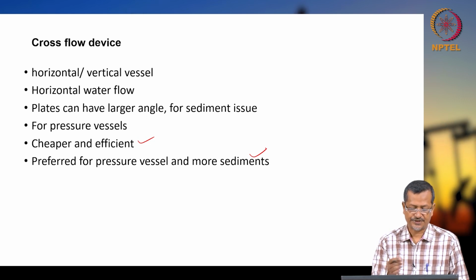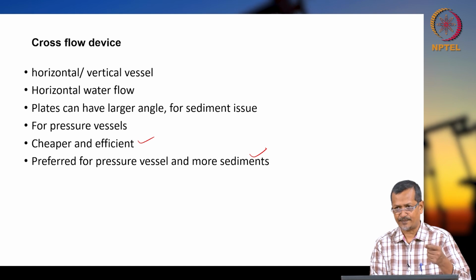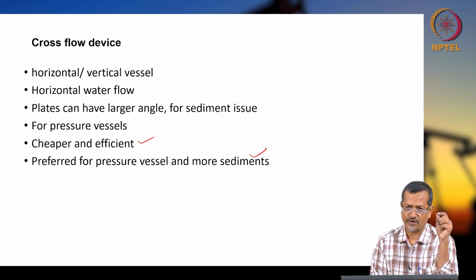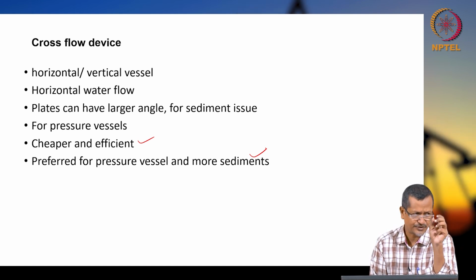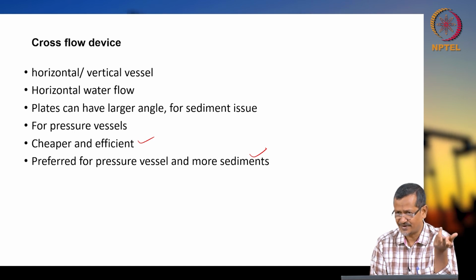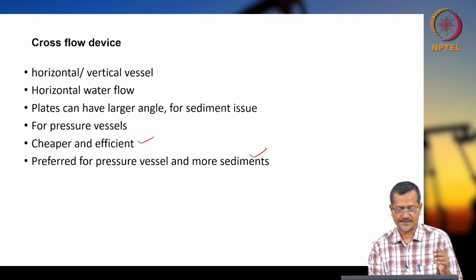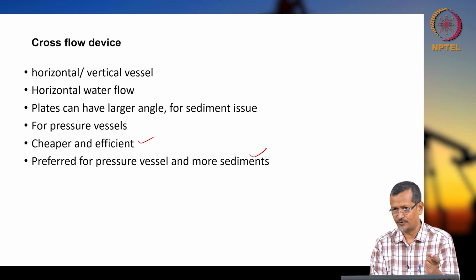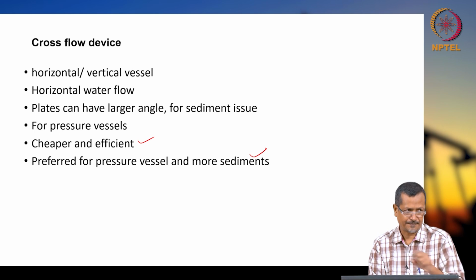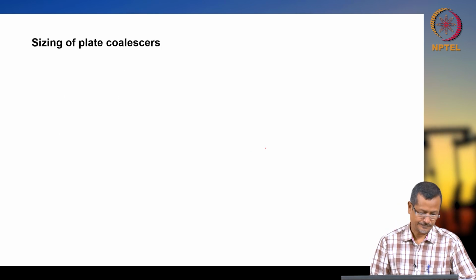There is a possibility of shearing the inlet oil. If shearing is happening, the separation will be difficult. Shearing means the oil particle is getting sheared, so the particle size will be smaller. Smaller dm means difficulty. Larger dm is better. So in some cases particle shearing is possible, and that will create much difficulty separating oil particles from water.